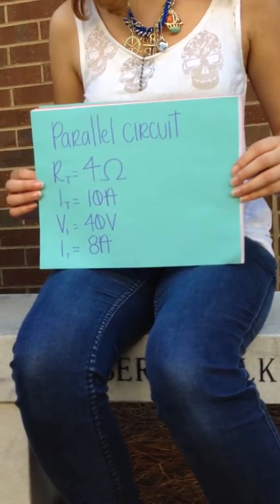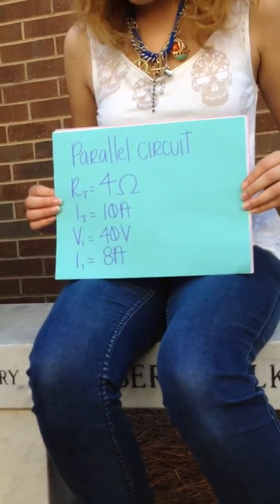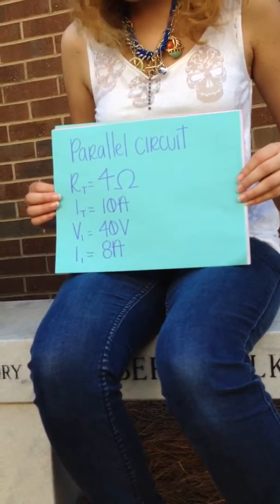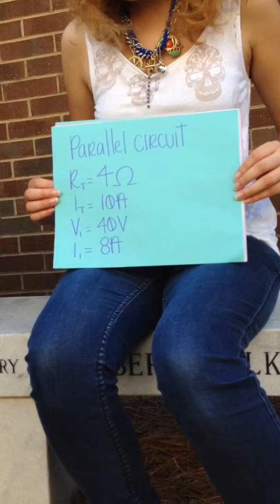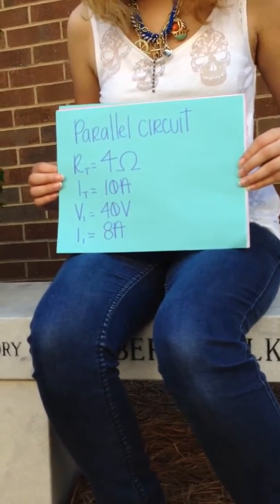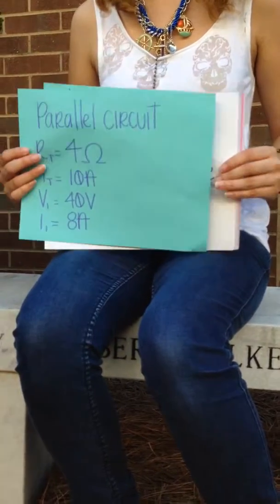So to solve our problem, it is a parallel circuit with RT of 4 ohms, IT, which is 10 amps, V1, which is 40 V, and I1, which is 8 A. The end.